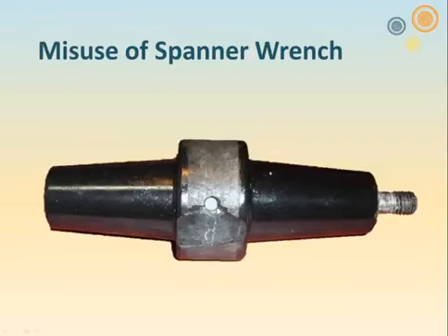The other problem is that by the time you've put the spanner wrench into the hole and put the torque wrench on it and you're all ready, the torque wrench is awkward because you might be hitting something, and the spanner wrench slips out of the hole a little bit, and then you put the torque on, you crack the epoxy.